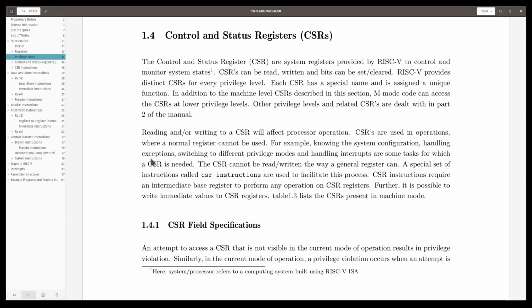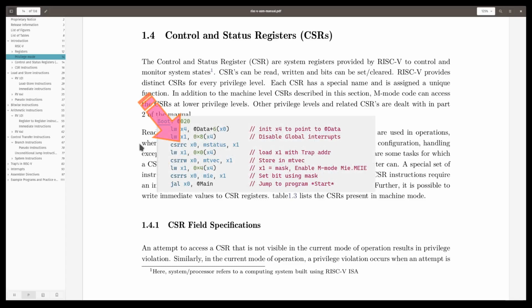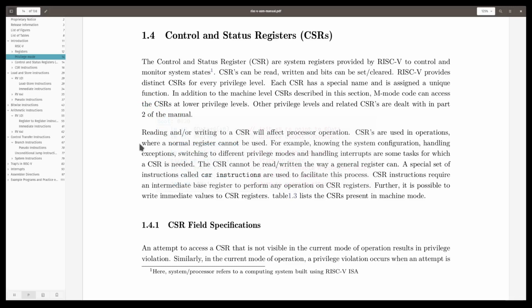They just say that as a black box, this is what must be reflected with the instruction sets themselves. So I went ahead and simplified the design just a little bit. The code's almost identical, but I reduced the code to just manipulating the global enablement and the M mode enablement only by the instructions themselves, and the pending bit is controlled by the hardware.